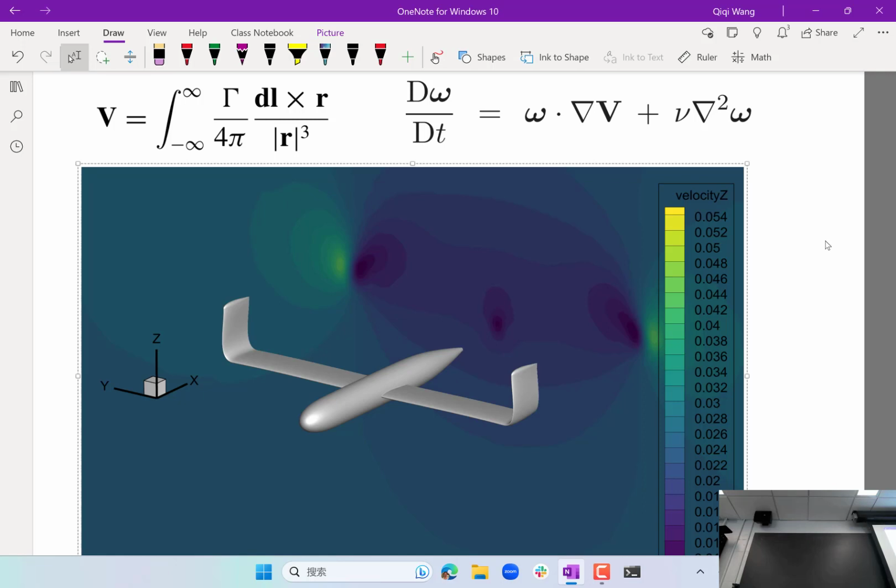And that means in order for the lift vector to rotate upstream, the lift vector has to point inboard. And for the lift vector to point inboard, you need a low pressure region inboard and a high pressure region outboard, right? That means the circulation around the wing has to be like that.